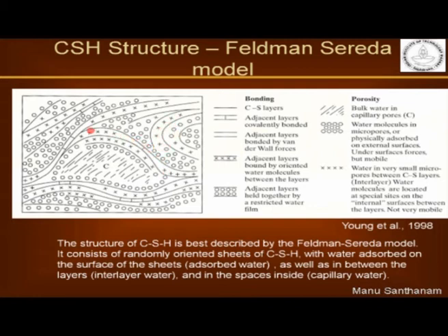And then you have these O's. The O is basically molecules of water that are physically adsorbed onto the sheets, in micropores or on the external surfaces of CSH. So you can imagine that when you are trying to draw out this water by drying, the CSH sheets will start collapsing or merging into each other. So there is going to be a very large volumetric shrinkage.